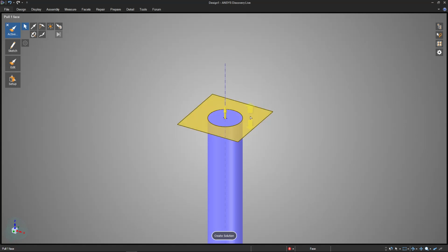One of the things that when we start to pull, you want to make sure this cube is solid. If I just select the outside here, it'll leave this flat, it won't pull it up. And to include both of those, I'll click one to begin with, hold down shift, and then click the other. Actually, it's hold down control and click the other. So as long as you have control held down, you can click any faces that you want to add.